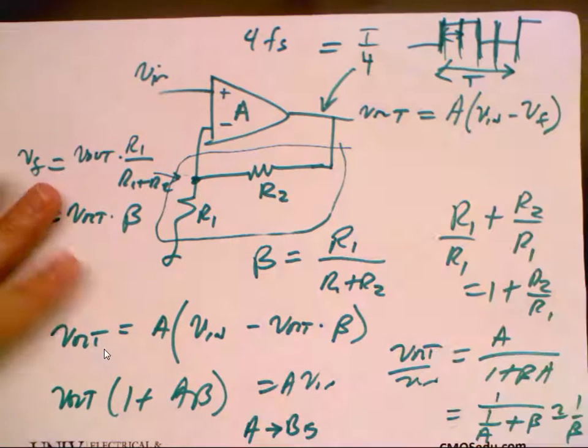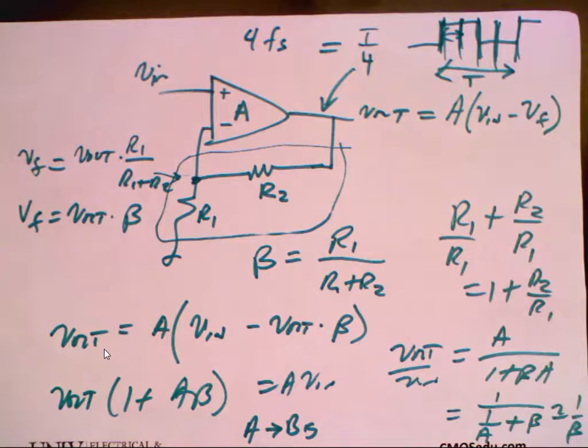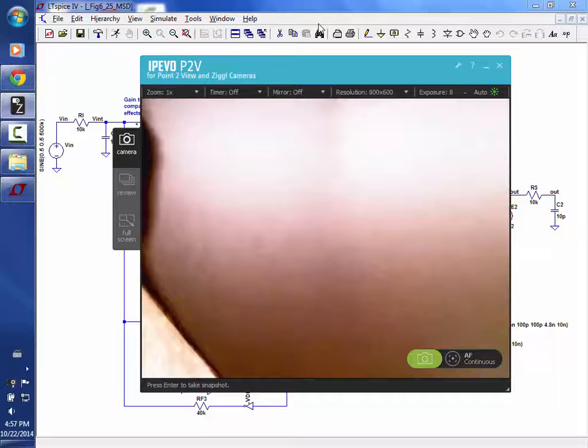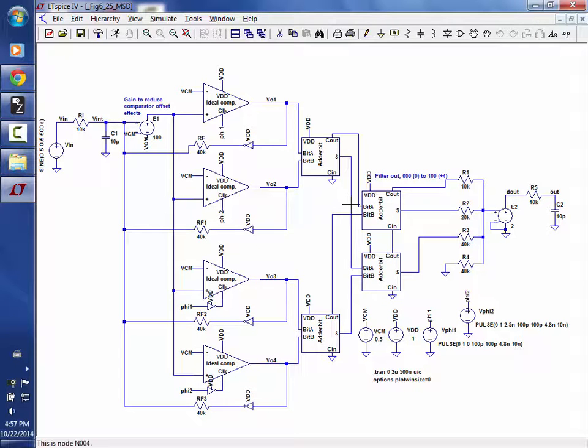Okay, so if I was generating the clocks with inverter delays and I had a 10 picosecond inverter delay, I could effectively get 100 gigahertz sampling frequency. So the benefit there is now if I'm at 100 gigahertz, I can really do some wider band conversions. Does everybody follow that? Okay, so if I go back now and I look at this, this again is a passive modulator. Let's go through and see how it works.